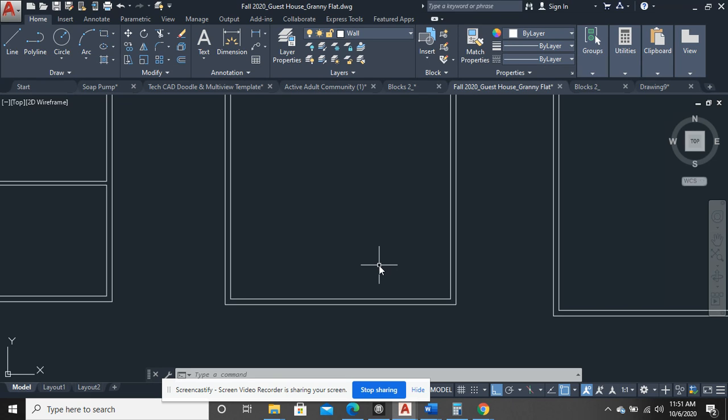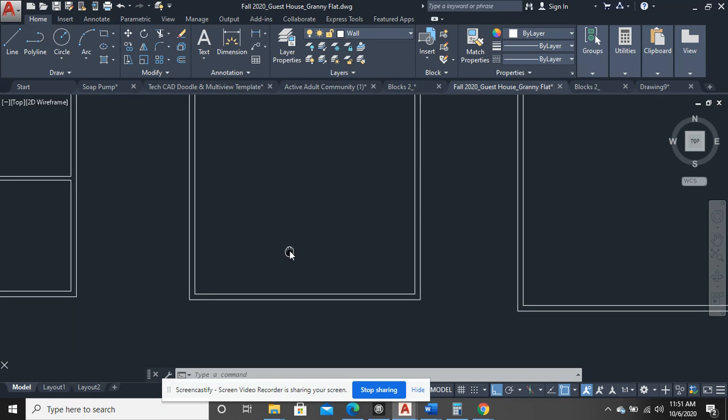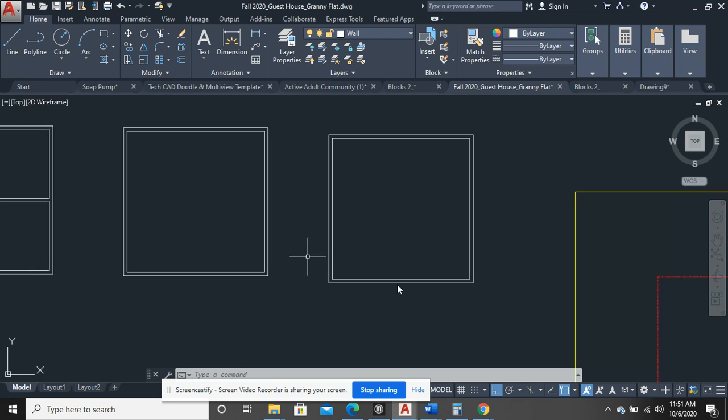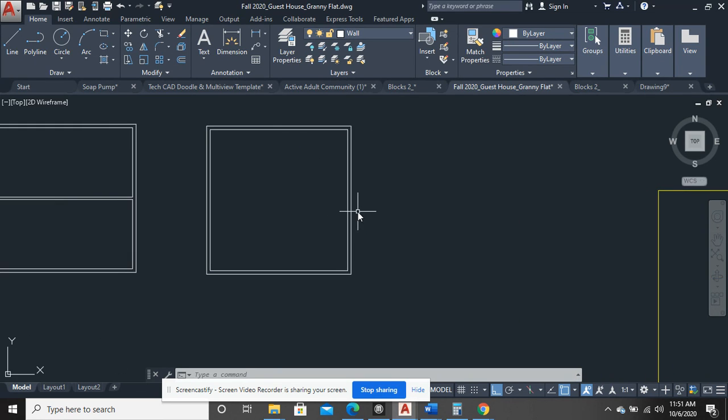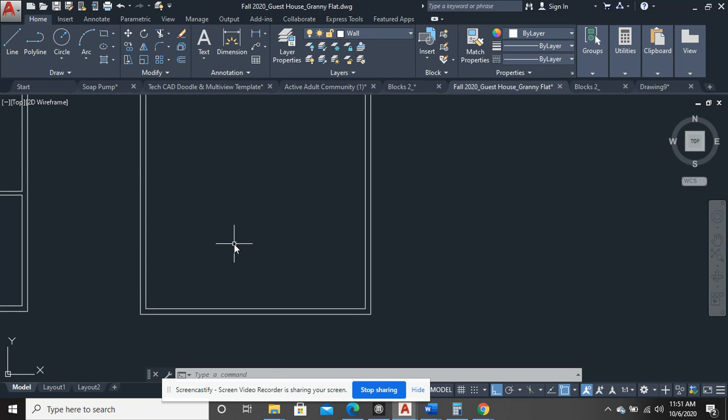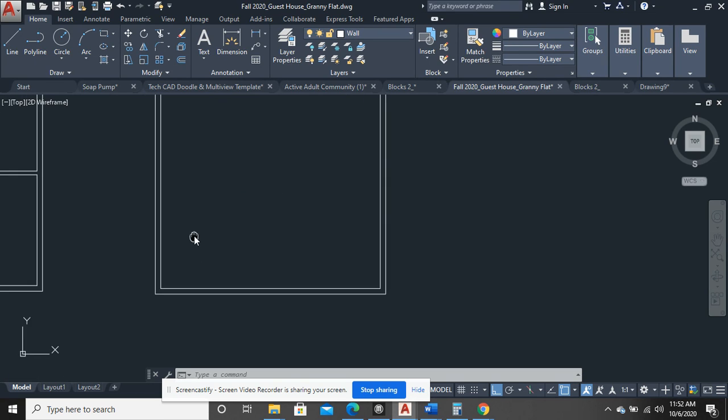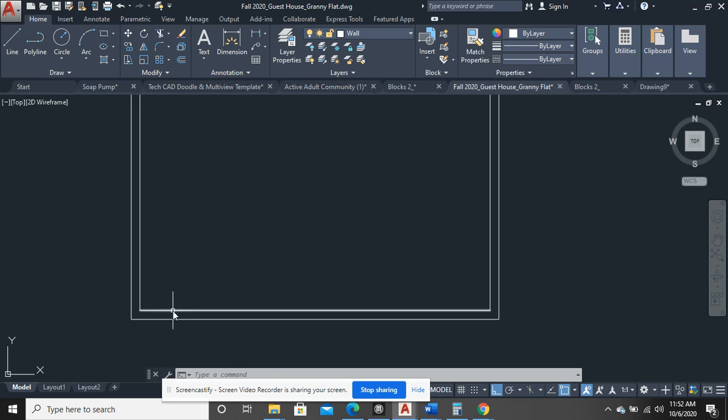So let's say I have to build a door. I'm going to build this same door, but I'm going to do it 2 ways, and this is the starting point. I typically plan my entry first. So if my entry into the house is going to be right here, I have to use a 36-inch door.